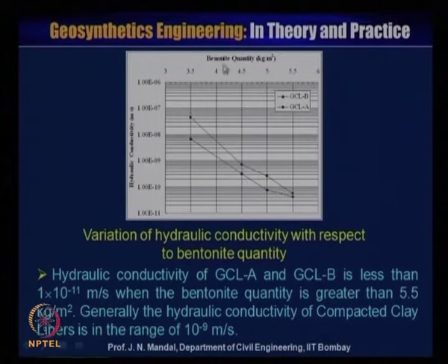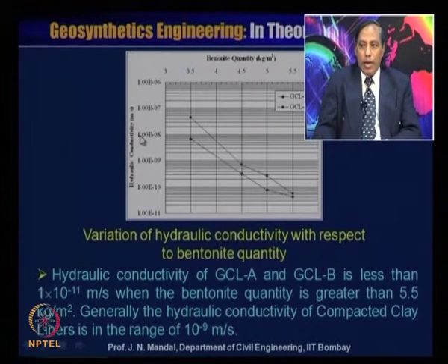This is the bentonite quantity, that is kg per meter square, and this is the hydraulic conductivity, that is meter per second.